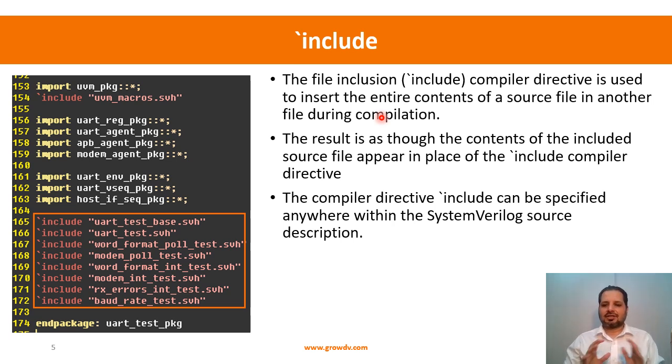That's what it does. It doesn't do it literally, but the effect of the `include is as good as doing the copy-paste. The result is that the contents of the included file appear in the place of the `include. It is a compiler directive, and the compiler directive `include can be specified anywhere within your SystemVerilog source description. I'm just showing one typical example.